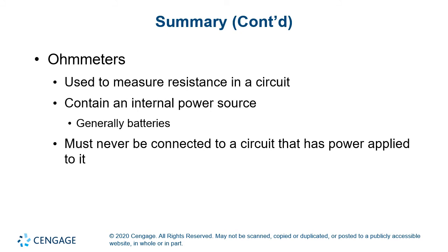The last of the standalone devices is our ohm meter. Of course, this is designed to measure resistance. It does have to have an internal power supply, right? Because the fact is we don't have the power on. When you're using an ohm meter, the power is off in the circuit, so we have to generate a small amount of power.